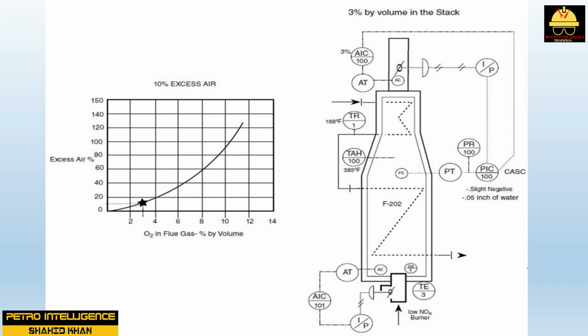specification. Some process heaters utilize advanced control instrumentation that maintains a preset ratio of air to fuel. For example, a ratio of 11 means that for each weight unit, kilograms or pounds of fuel, there are 11 similar units of oxygen being supplied. Higher ratios indicate that there is more excess air. A lower ratio translates to less excess air.